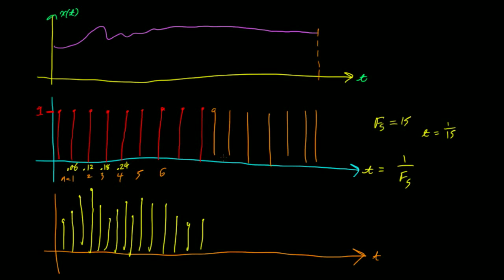John, what if this were not a cosine, the blue signal? What if it were like a triangle? How would it be able to interpret the difference? Well, we want to look at a cosine now because it's only got one frequency in it. If you're looking at triangle waves or square waves, how many frequencies? More than one. Infinite, right? So no matter what happens, something's always going to get aliased.